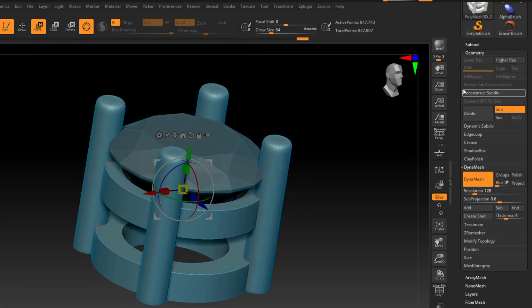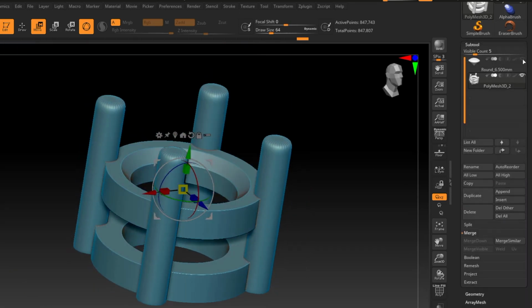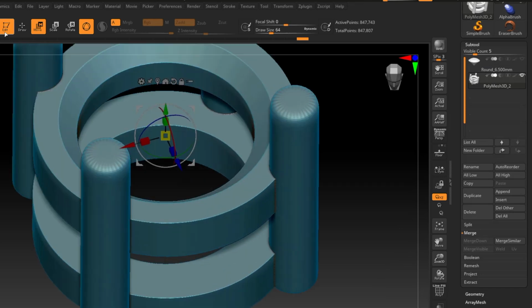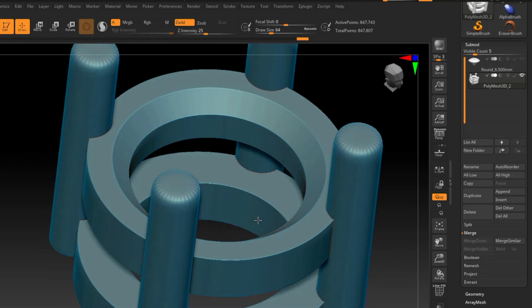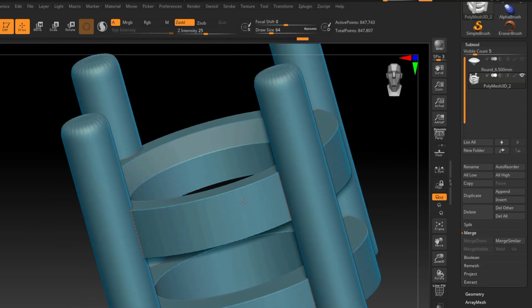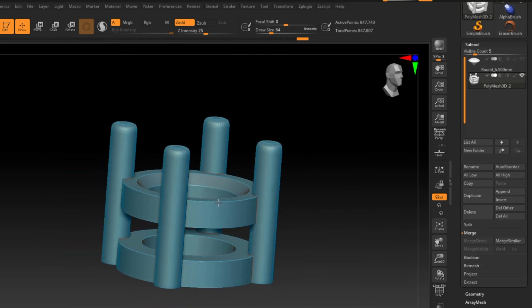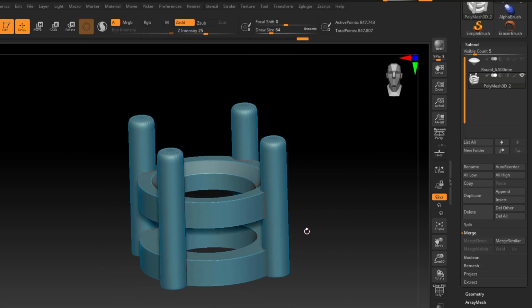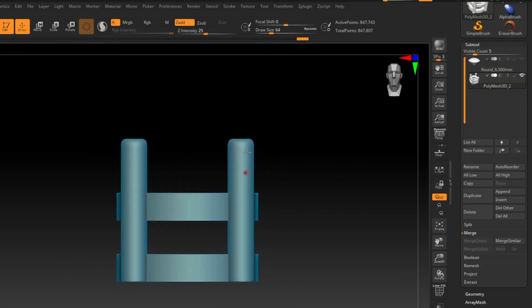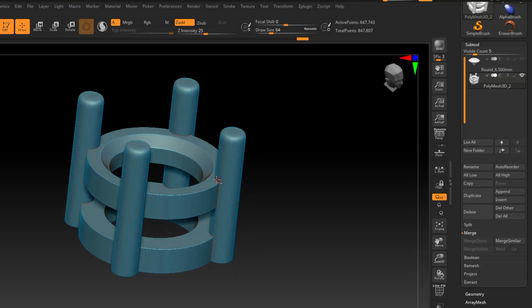So this is pretty good. In fact, if I turn off the stone real quick, we can get a better look at it, and turn off the gizmo. So everything's looking good right now. But there is one more thing I want to do just to make this look a little nicer. Right now we have this setting that's very much straight, but most settings have a taper to them. So we're going to add a taper to this one as well.